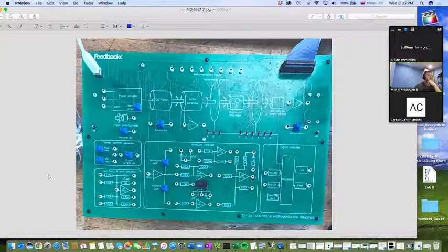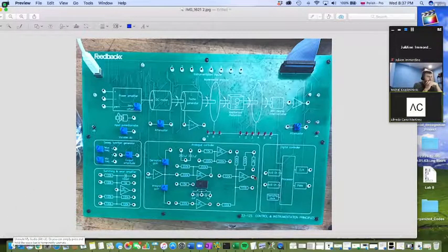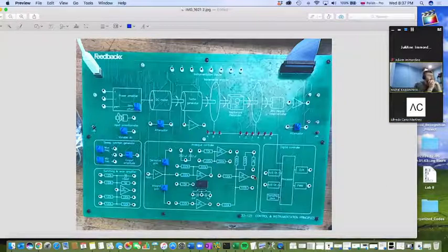In this case, this op amp serves really more for buffering because you are combining 4 different signals that come from very different op amps. You want to stabilize the thing, so we include this op amp there for stabilizing, for buffering the signal. You see the gains are not very different, right? You could make this a gain of 1, or you could just boost it up a little bit if the application requires it. You can think of this op amp as a stabilizer op amp so that you can have more robust signals coming out of the full PID.